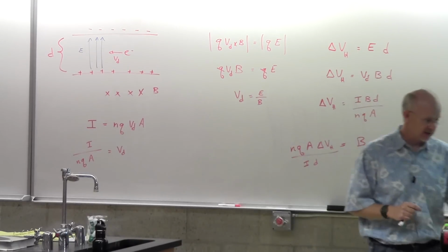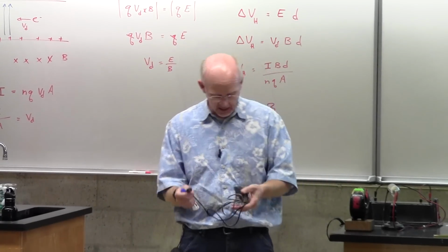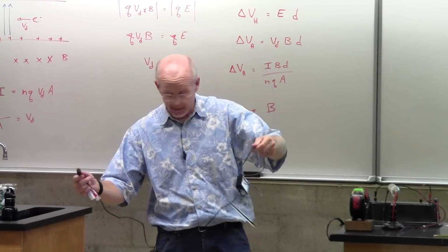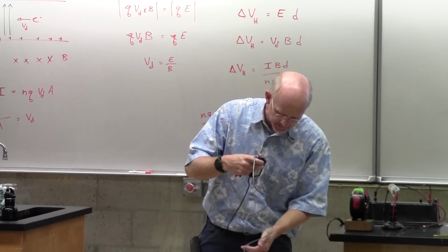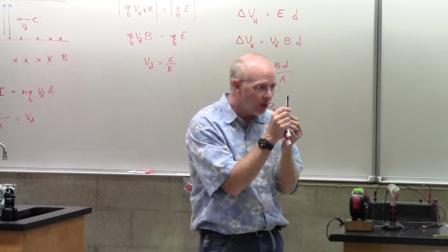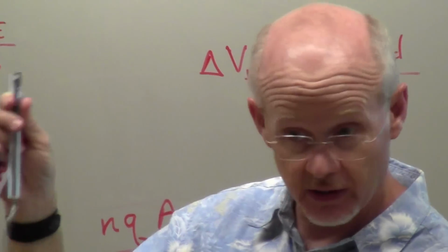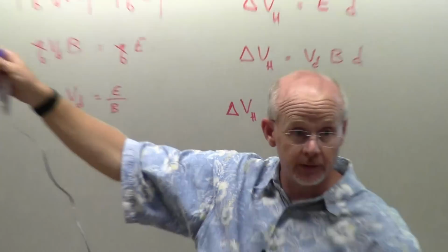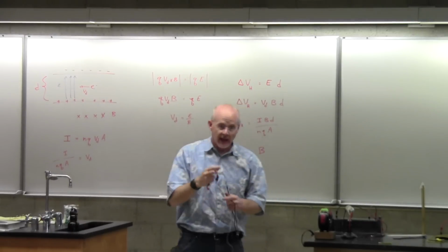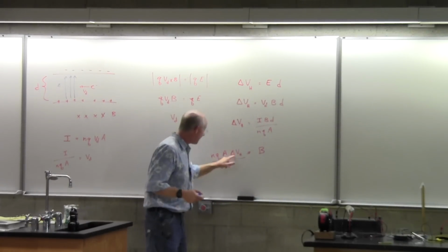We will have this little tiny device, and you can see the connections from the equipment you've been using in the lab. This obviously goes into our ULI, and this is our Hall probe. In this Hall probe, you will see a little white dot, and buried under that plastic white dot is a metal strip. That voltage is fed into the computer. It's not much voltage, so this is a little amplifier. We amplify the voltage, send that into the computer, and given all these other factors, we can then say, all right, we've got the voltage.